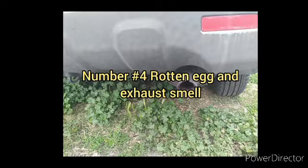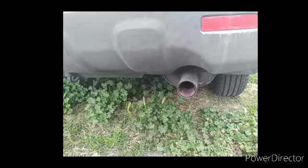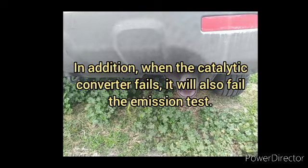Number 4. Rotten egg and exhaust smell. When the exhaust is blocked, it is usually caused by a failed catalytic converter. When the catalytic converter fails, it can emit a sulfur smell. It can also trigger catalytic codes such as P0420. In addition, when the catalytic converter fails, it will also fail the emission test.